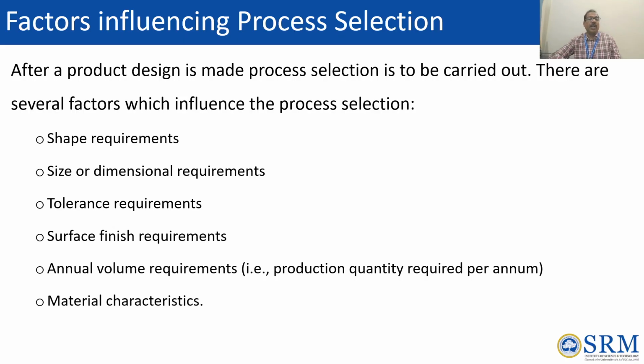Then what kind of tolerance do we need? Whether plus or minus 0.05, or 0.01, or 0.2 millimeters. Depending on the tolerances required, we need to choose the machinery and tools required for that.